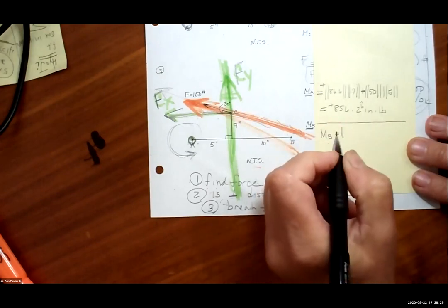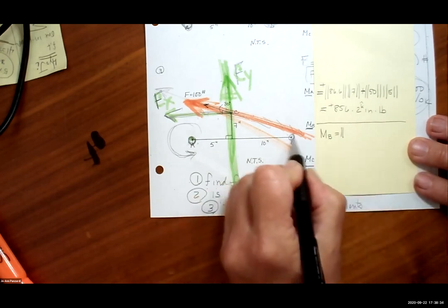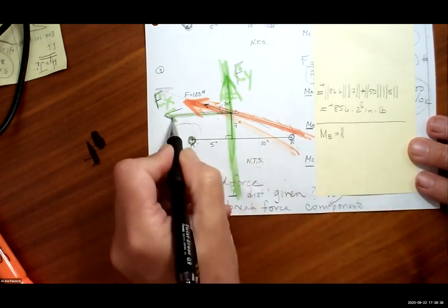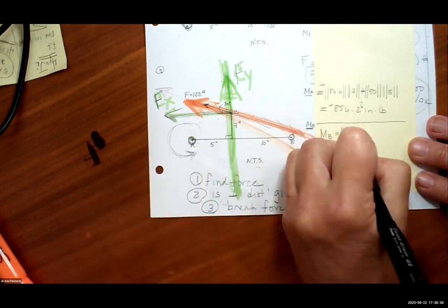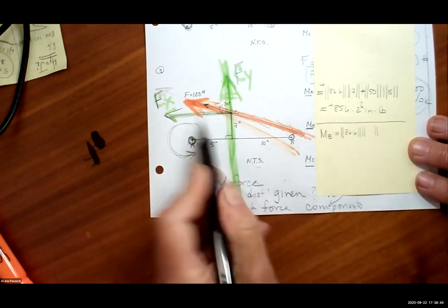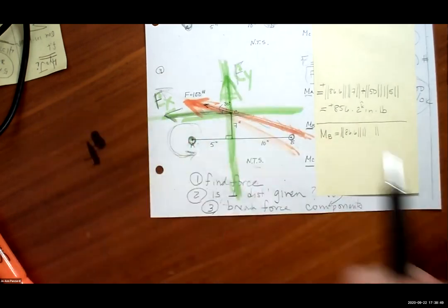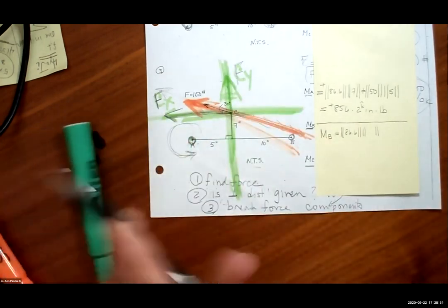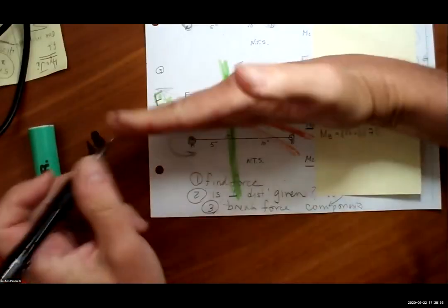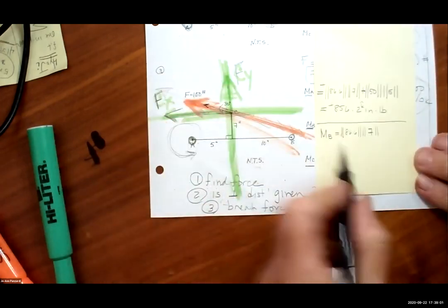So I am up to Liam. Liam, I'm calculating the moment about B due to Fx. So Fx is 86.6. What is the perpendicular distance from Fx, here's Fx, to point B? 7 inches. Great. Positive or negative? Fingers in the direction of the force, palm goes towards the point I'm finding a moment about. Positive or negative? Positive. Great.